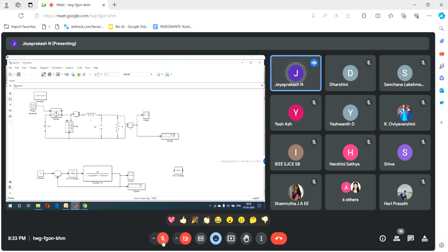So we will easily reduce the maximum peak overshoot. This is possible with the help of the transfer function. Here we have only one parameter, that is the zeta value. You have studied this in your second unit of control system, time domain specification. That zeta value decides whether the system is underdamped, overdamped or critically damped. When that value is changed, we get our desired output value.